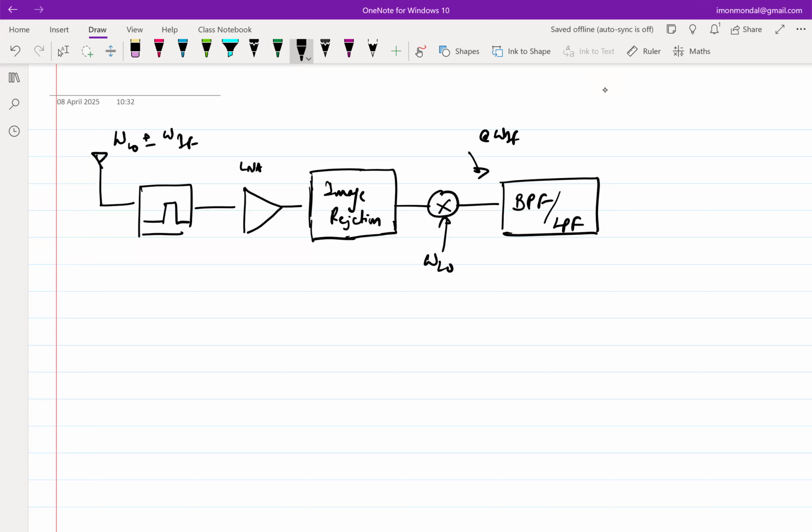The only downside is that your baseband bandwidth is, in most cases, probably a couple of megahertz, 10 megahertz or so. If that is the case, and you have a significant part of the baseband spectrum where you do not have any information, then it's better to use the band pass filter. Otherwise, low pass is also fine.